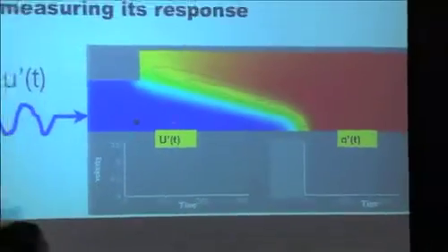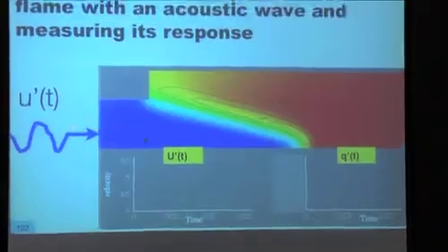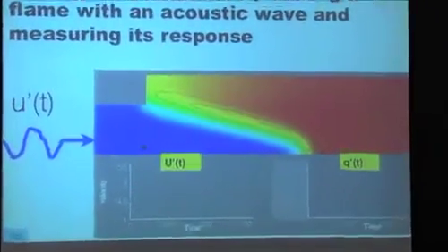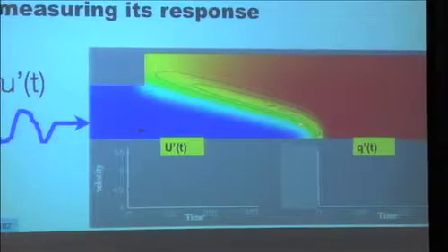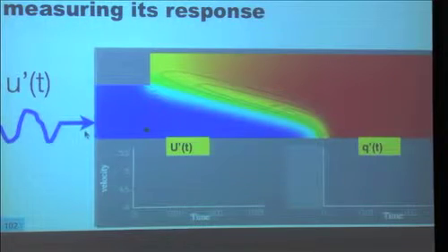How do you obtain the flame transfer function in practice? Okay, so that's an example here for a laminar flame stabilized here behind a wedge. You have cold gases, hot gases. The principle is very simple. You send acoustic waves in this flame that will give you an oscillating velocity signal, and you measure the total heat release here versus time. So we did it here, for example, for